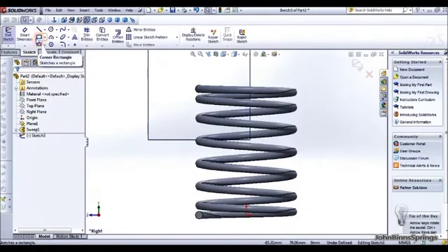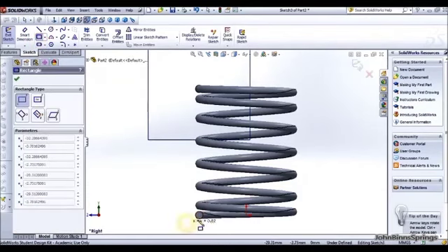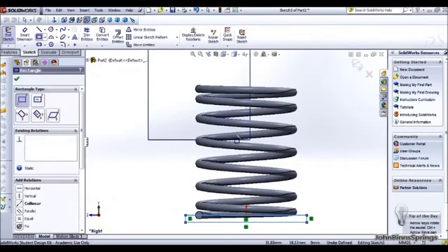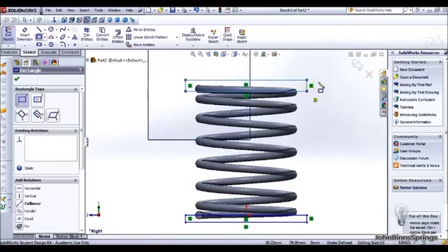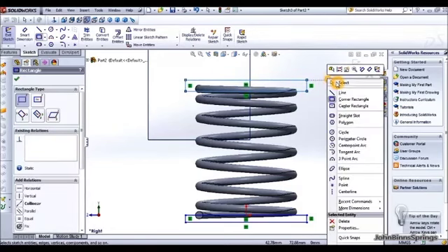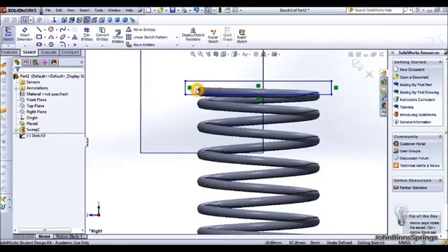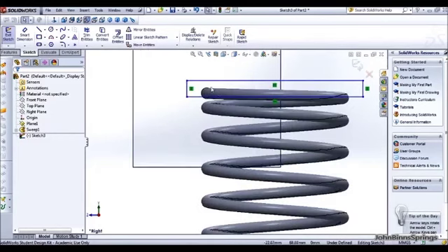And what I'm going to do now, I'm going to select the corner to corner rectangular tool and just draw a square on the bottom. I'm also going to do one on the top. This will save time later on. Right click and select to jump out of them commands. And we now need to measure the distance between the bottom point and the rectangle we've just drawn, so we know that we're taking off 70%.